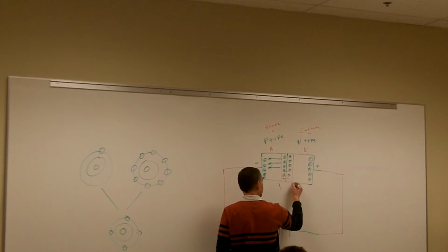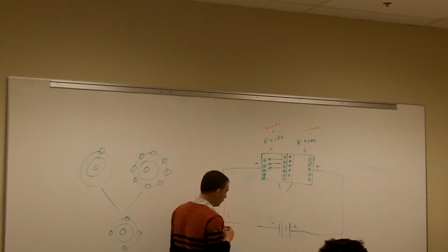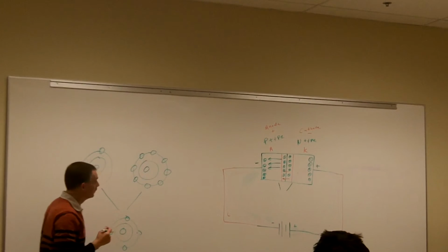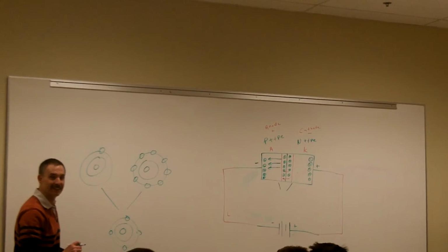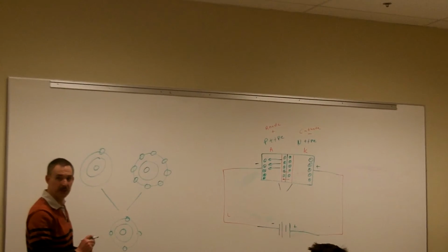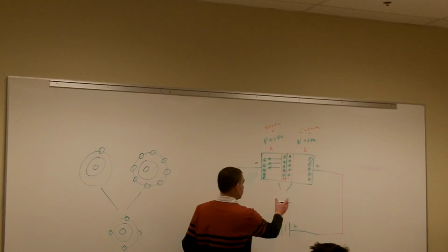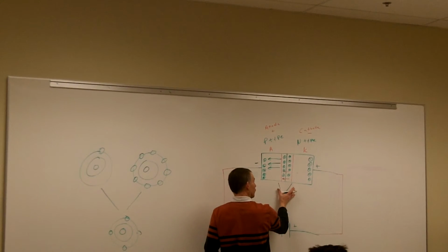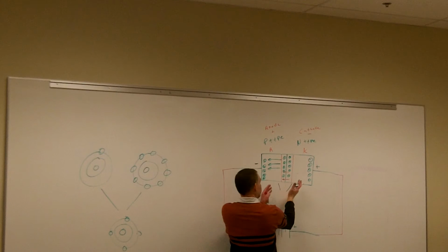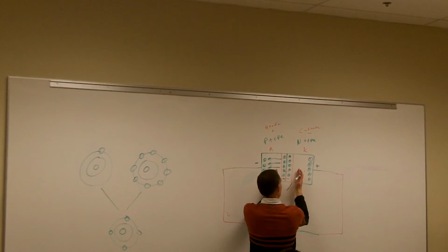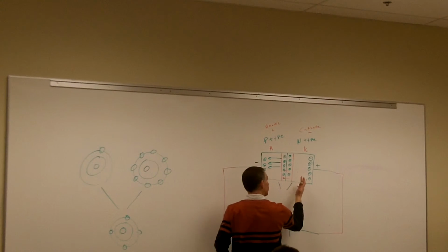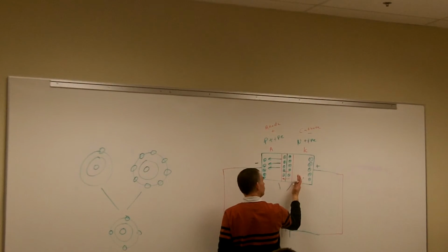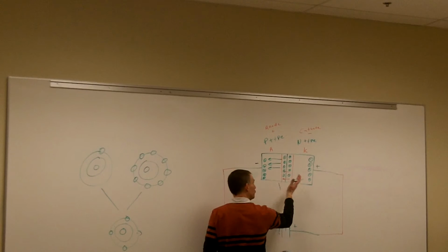that voltage, we call it the barrier potential because remember, what's our definition for voltage? Potential difference. Yeah, the potential difference between 2 points, okay? So that's why we call it our barrier potential, because it's that potential difference between the 2 points. So the difference between my N-type and my P-type. And it's always going to take a consistent amount of voltage to jump that barrier.